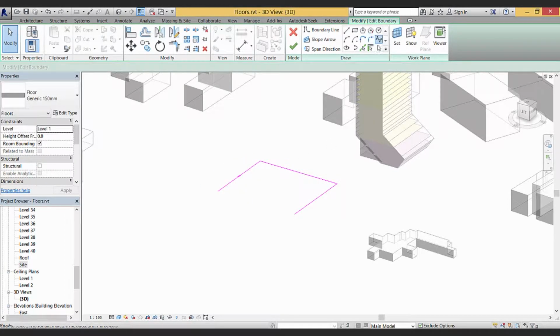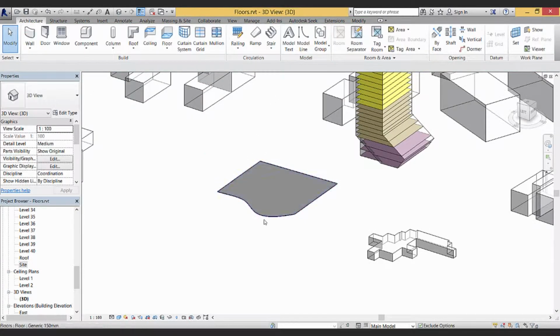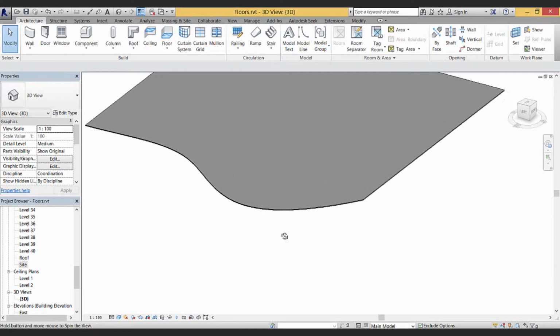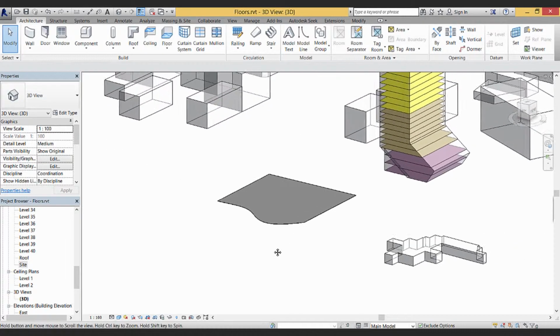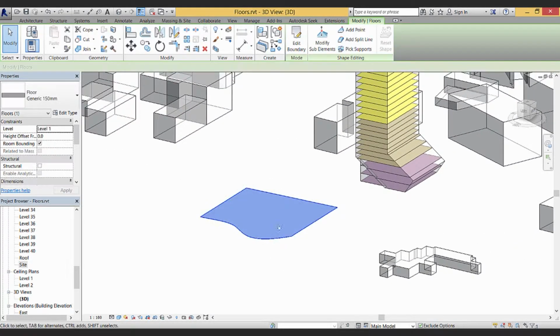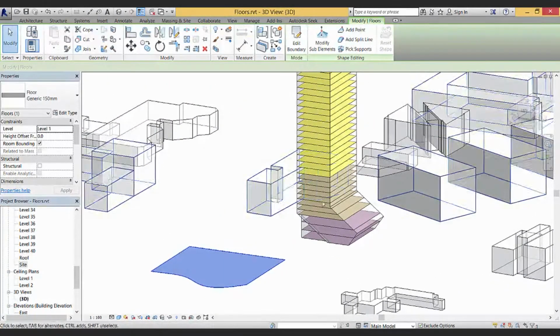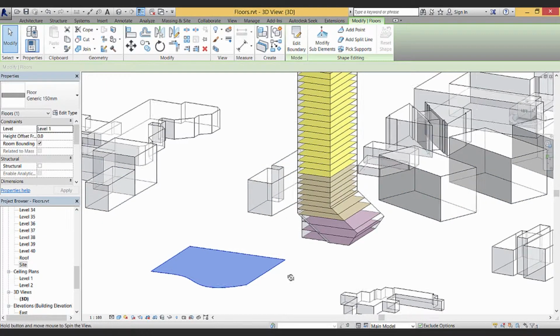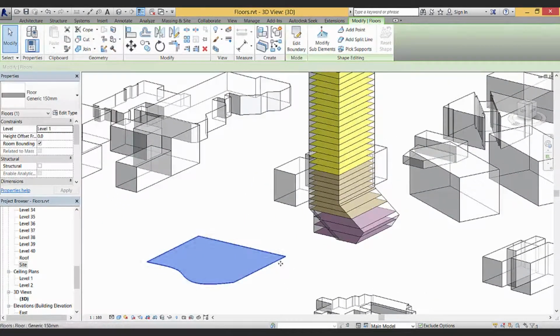Let's try to just draw a spline. So if you go spline, spline, spline, spline, and then finish, you have drawn a Revit floor with a splined edge. So this is like the floor tool in 2 seconds. If we have mass floors inside a Revit mass, like we have, we can generate multiple floors pretty quick.